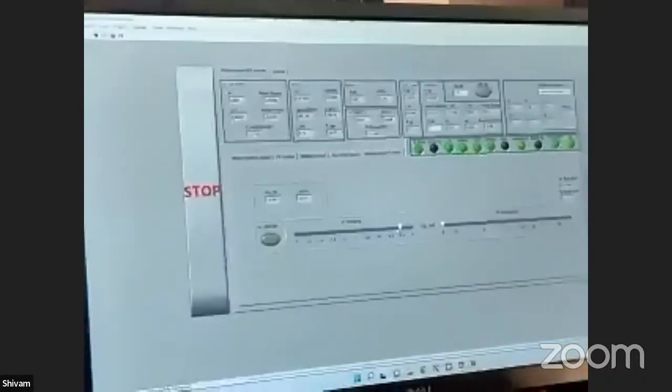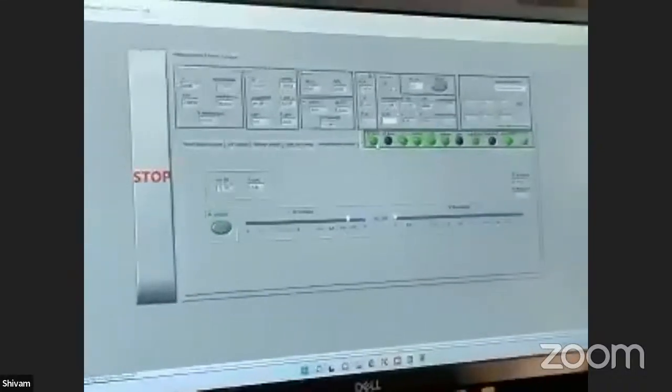So now we turned on the supercapacitor from that side. Now I will turn it on from here. Okay. And I can either charge or discharge this from this end. So suppose I want it to charge. So you see SC buck is on. SC buck means supercapacitor buck. So power is coming from the grid and you see the current has turned negative.